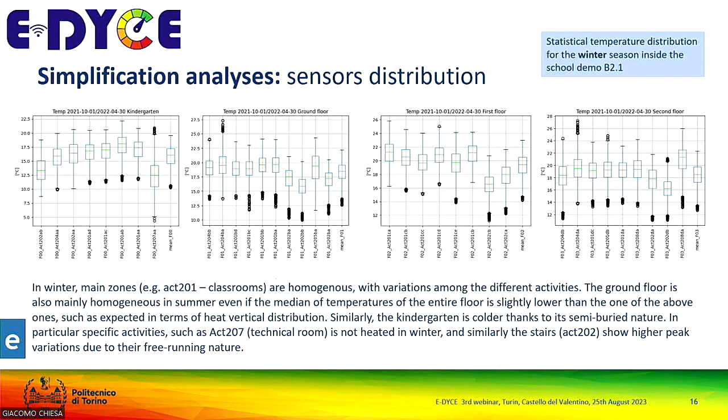It's immediately evident that we have a general behavior floor by floor. So in some way, especially for temperature, we can think of reducing the sensors, also because there is one thermostat. Roughly speaking, the south-oriented rooms will act similarly if there are people in them. We have cases in which you see a variation, but those are other types of rooms with different schedule profiles of use.